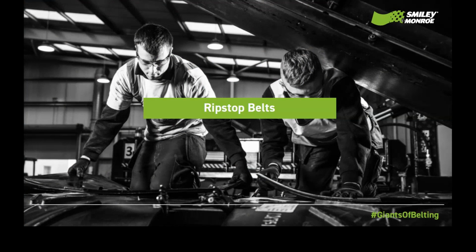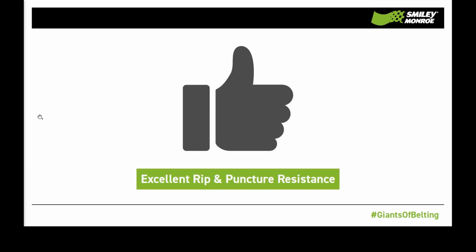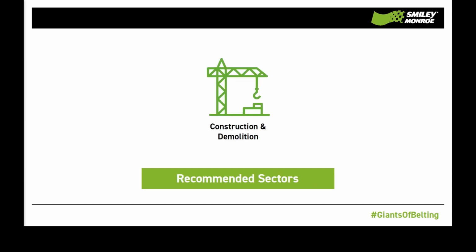Next, our Ripstop belting consists of steel wires, which is used as an extra ply in the carcass of the belt in order to protect the EP fabrics from longitudinal cuts, while the ability for trough formation is maintained. The reinforced steel wire mesh creates excellent rip and puncture resistance and offers longer lifespan. It is suitable for machines with overband magnets but not metal detectors, and is widely used in construction and demolition industries and often used for crusher collection belts.